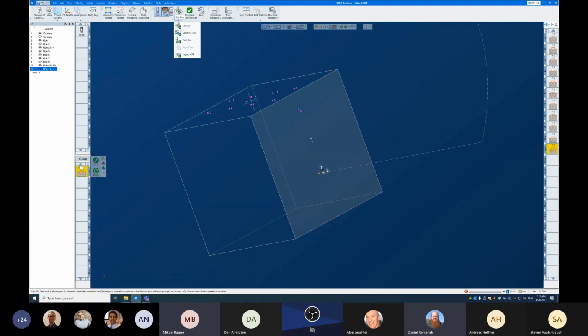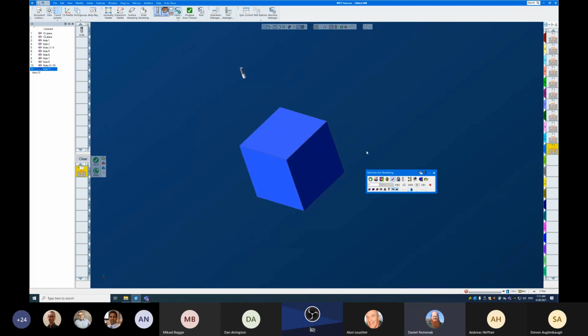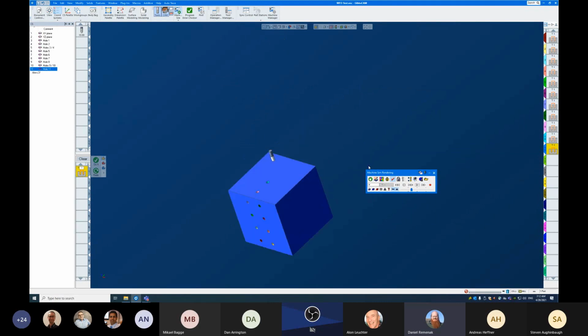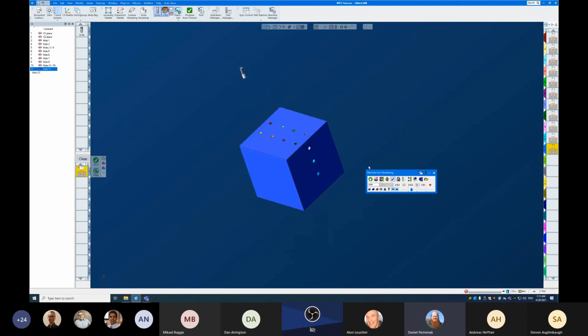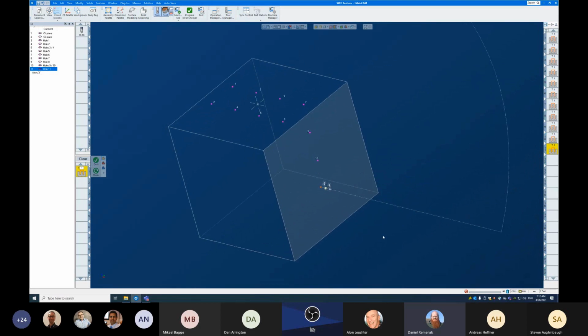Yep. So if we just look at what this part is doing in part space, we can see it's drilling holes. There's nothing really fancy going on here. If we look at machine space, the top isn't surprising. This is the surprising part. We're using alternate solutions for these holes. That will become important as we look at what's happening on this part and what the old system would have done, because what it would have done is crashed your machine, and that's bad.